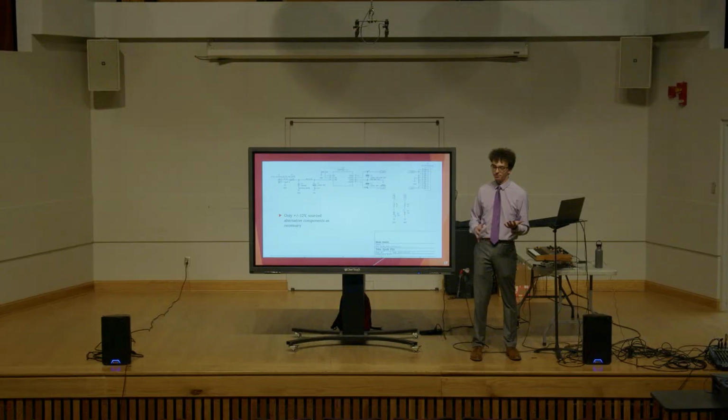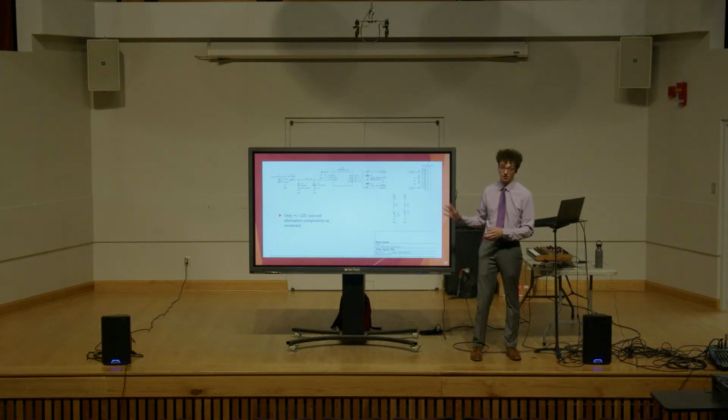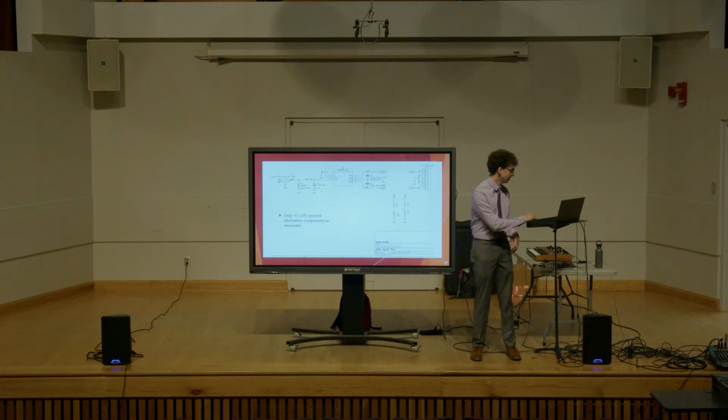But unfortunately, it is only plus and minus 12 volts, which worked great when I was just doing analog circuits. But now that I'm implementing digital control circuits and need a 5-volt source or 3.3 volt source, I'm now using, or having to use, voltage regulators for that are a little bit less stable, a little bit more noisy, which isn't lovely. And so I might have to go back to the drawing board on this circuit and implement a digital voltage level source that I can pull from. But that will be for later.